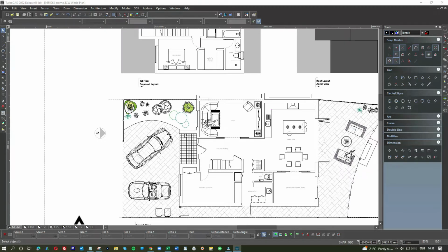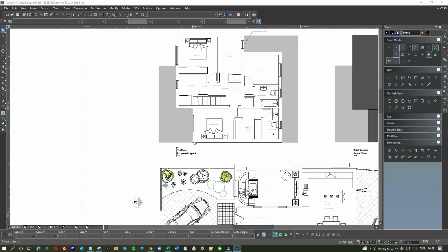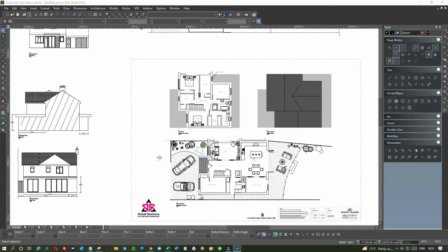We brought forward an exterior open porch, and we brought forward what would have been on the garage area. Now on the upstairs we did the opposite. We recessed the first floor, and the whole idea is to make this extension up here subservient to the main house, otherwise we'd never get planning. So we set it back a meter. It comes out to the same amount here, but we recessed a meter, which is always good.